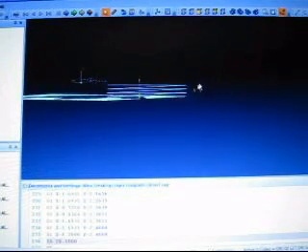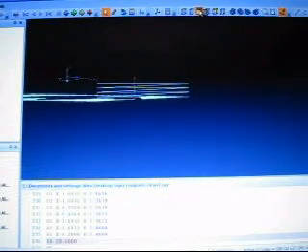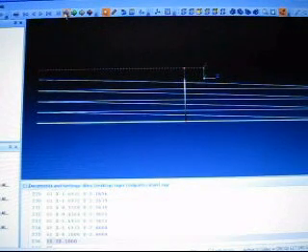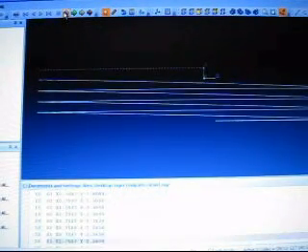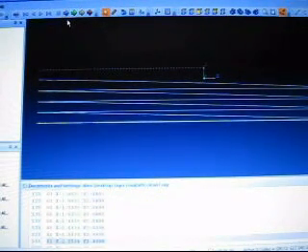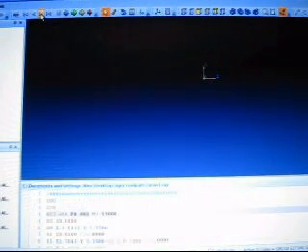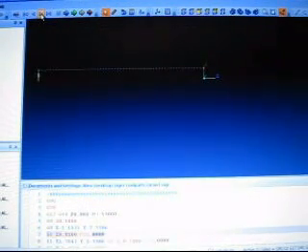Okay, so that's all I want to show you. Basically a quick little ramping routine. So it ramps safely down into the part with a non-center cutting bit. Okay, this is just an El Cheapo Harbor Freight tool bit. So it's a pretty much of a straight. It's not a helical end mill.